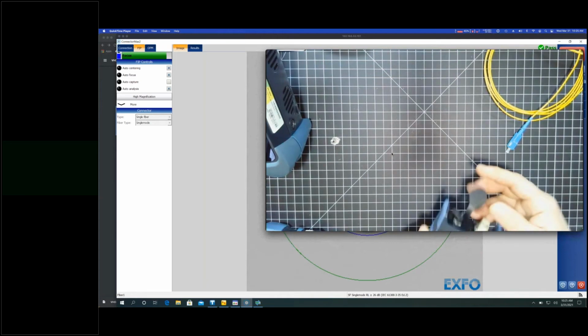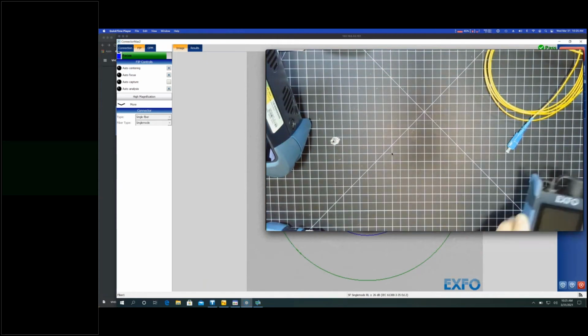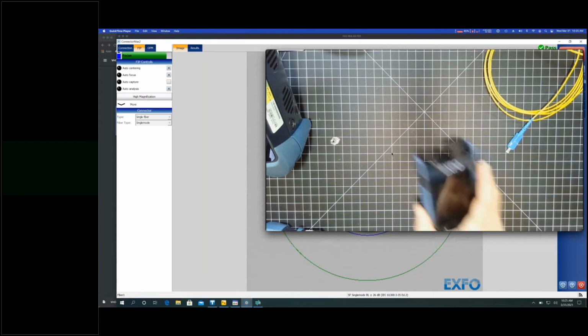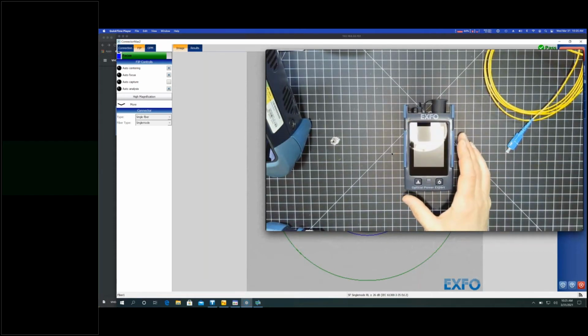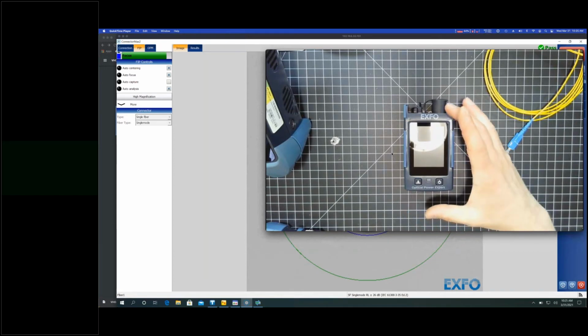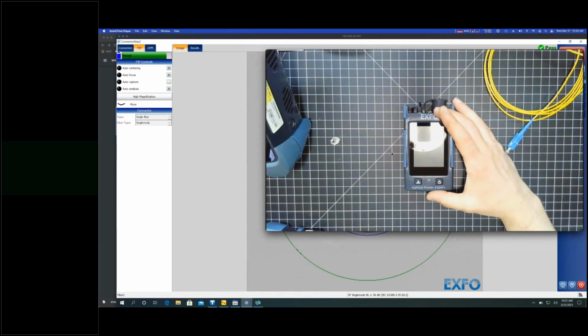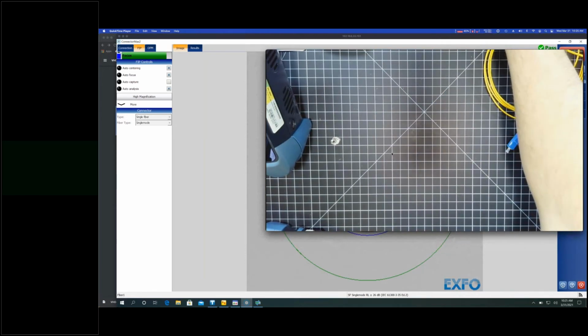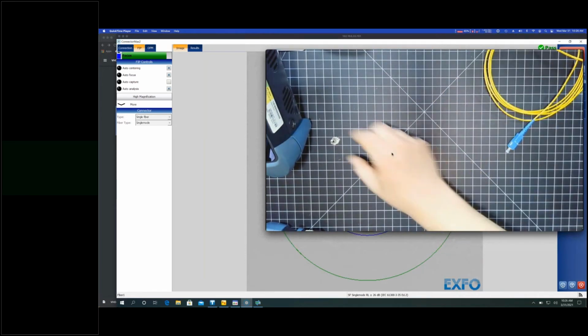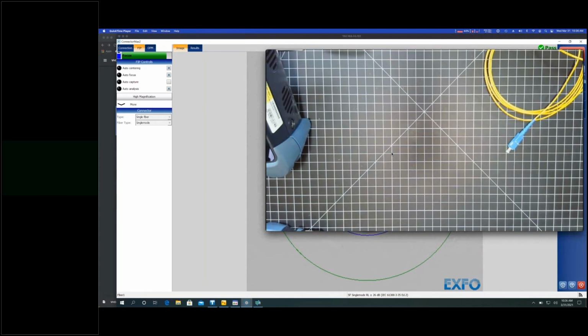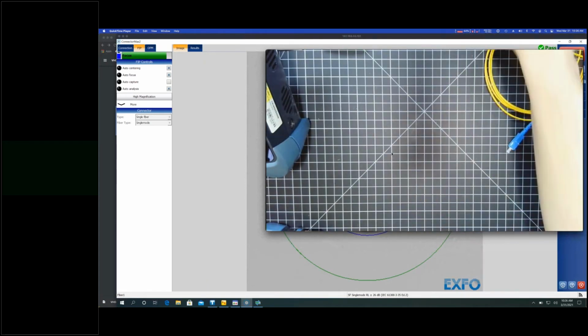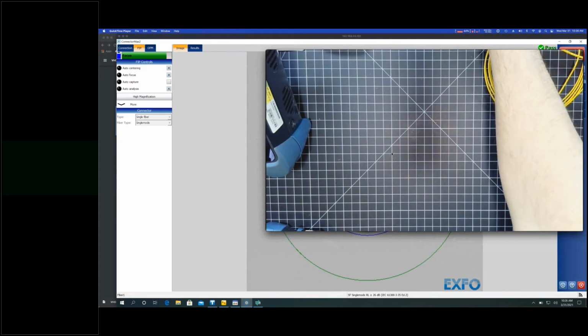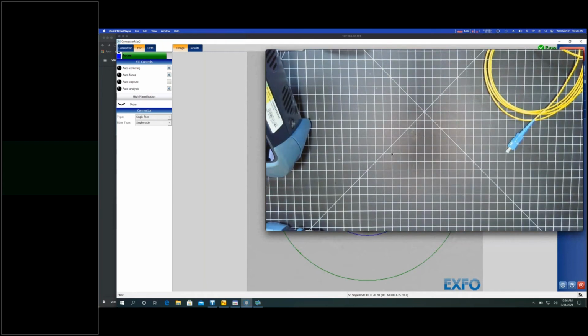But typically it's going to be from your CO equipment. Now, you could also use a simple power checker to accomplish the same thing, but we're not going to have the same level of accuracy as an actual power meter. So power meter, super handy, great for fiber to the home technicians to check for power. They can do some referencing and some absolute or relative power readings.